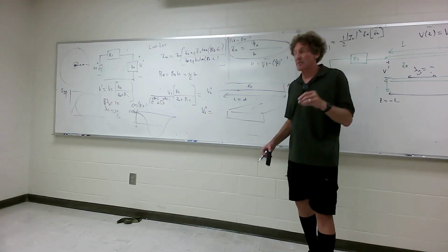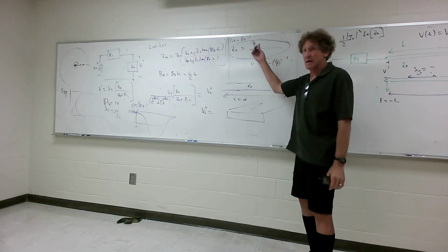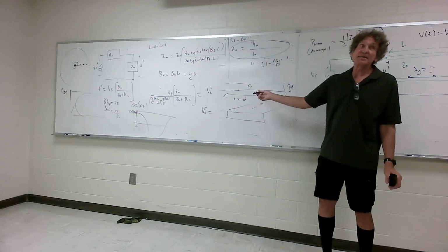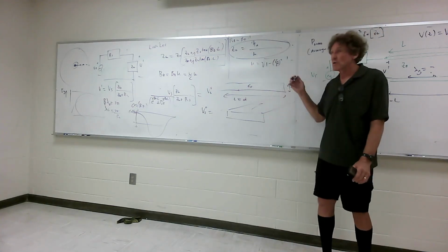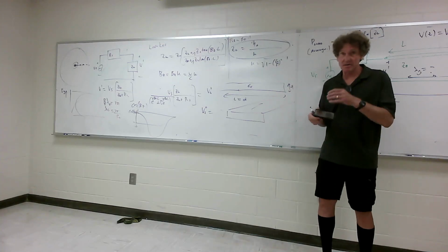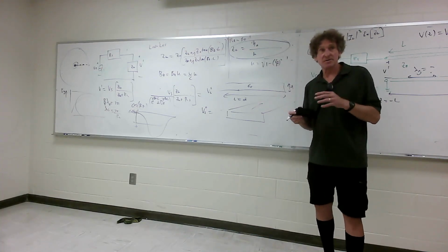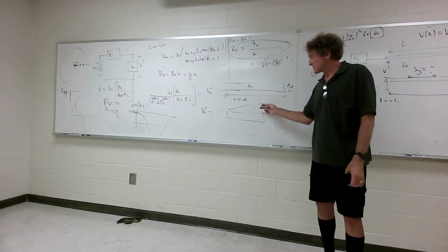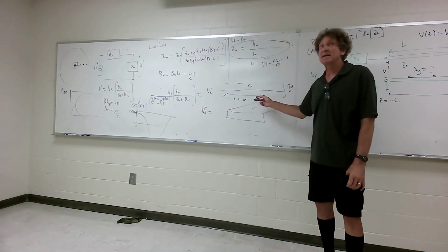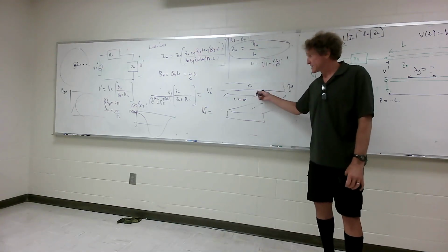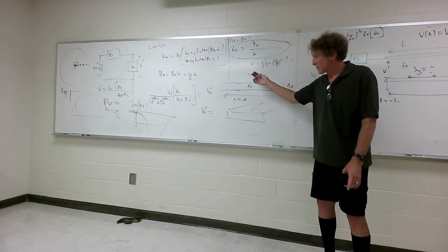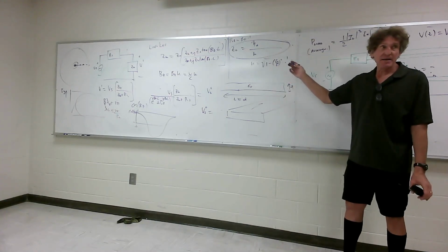Now, that field is not propagating away. It's propagating, in a sense, it's not even propagating, but it's propagating along the z-axis. This is a hard thing to really appreciate as you see an illustration or a little cartoon of this stuff in real time. That's called an evanescent wave, but that energy is not propagating that way. It extends outward, but the whole wave is propagating down the guide.